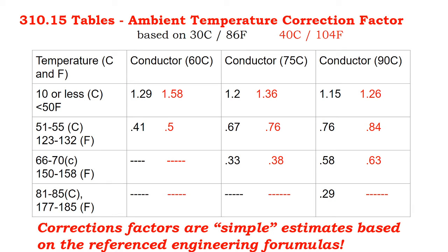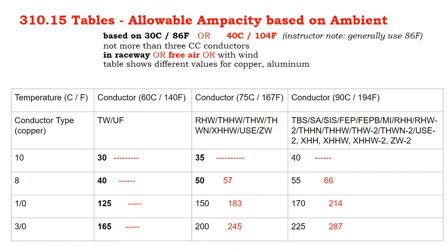Different cables have different temperature ratings. And so what adjustment factor you use is based off what material you select and what the material temperature rating is. Higher rated temperatures have less derating than lower rated materials at lower temperature ratings. In something like solar, you're generally dealing with high temperature ratings, but if you're using off-the-shelf parts from Home Depot, you're dealing with lower temperature ratings. And so which temperature level you do your calculation at adjusts these fudge factors. We'll talk about that later.